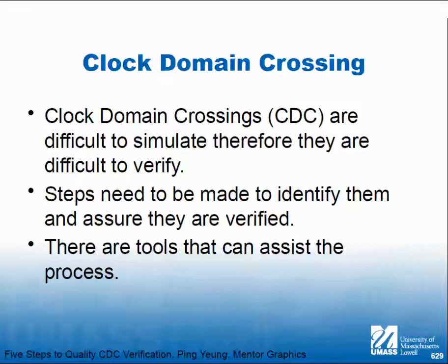So if your models have a picosecond resolution, so you have an inverter and the delay through the inverter from a low to a high is, say, 25 picoseconds. And from a high to a low, it's 32 picoseconds. I'm just making this up. So in that case, if the simulator is set to picosecond resolution, it will actually measure those exact times.